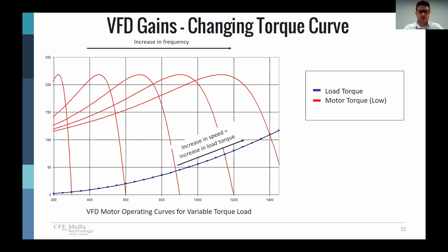If we look at the same system being run by a frequency inverter, there's a different torque versus speed curve for each speed set point. But what is very interesting is, we look at this, for every speed that's lower than the design speed of the motor, the way the load curve is shaped, the motor is actually very underloaded. And when the motor is underloaded, we'll explore a little bit more when we talk about that in the next step. When the motor is underloaded, though, it's operating very inefficiently.